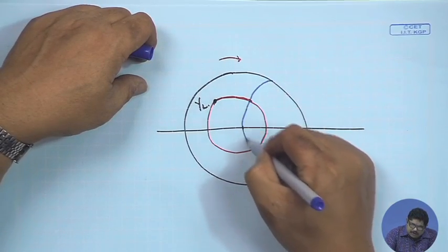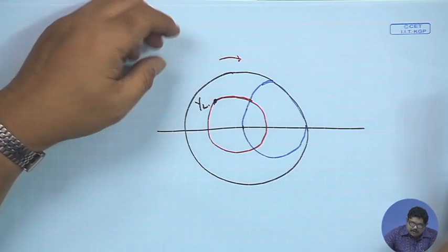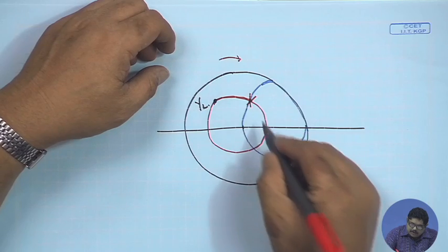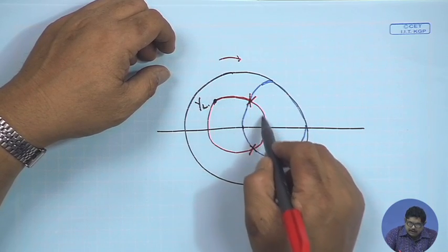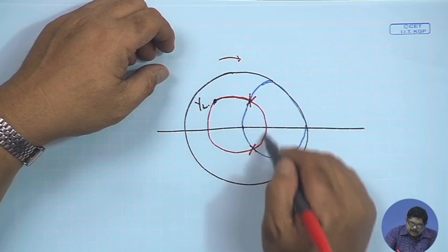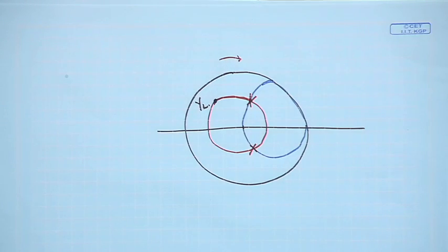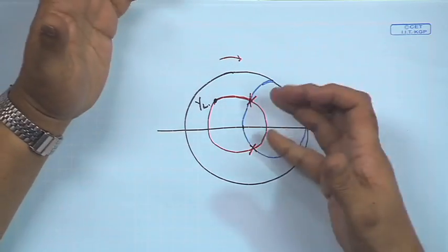This is the constant conductance circle, let us say, in the Smith chart. So, there I can come. Here I can either come to this point or I can continue and come to this point. So, these are the two solutions. In one case I will come like this, in another case like this. Now, it is up to the designer, because the frequency response of these two solutions will be different. So, from frequency response you can decide which one you will take. Also sometimes construction difficulty etcetera can tell you.